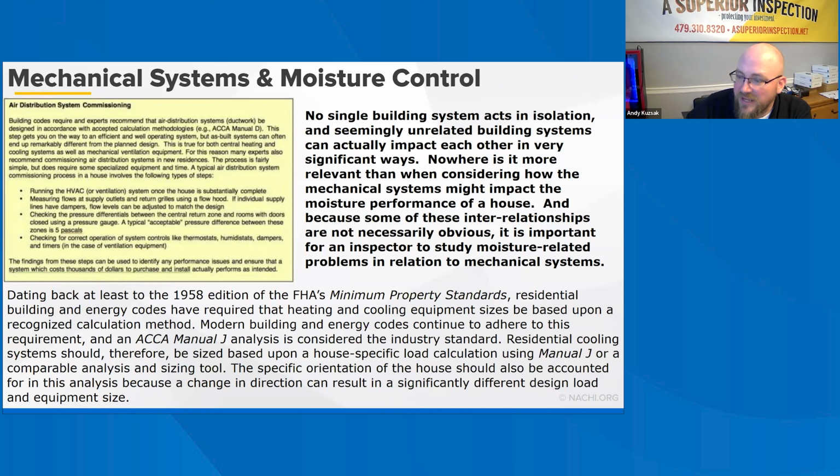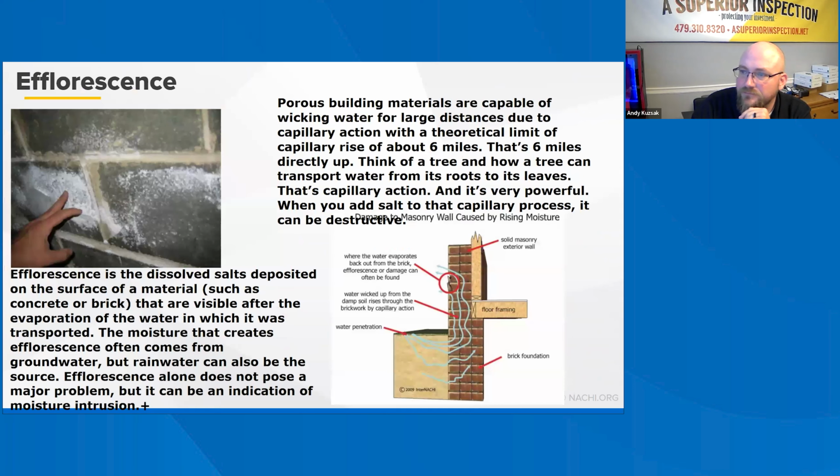Finally, exhaust fans are rated, like 50 CFM, based on a limited amount of back pressure due to the type and length of the ductwork and bends in the ductwork. Therefore, duct lengths longer than 25 feet, less 5 feet for each 90-degree bend, should be avoided unless appropriately designed. If long duct runs are unavoidable, larger capacity fan units should be used.